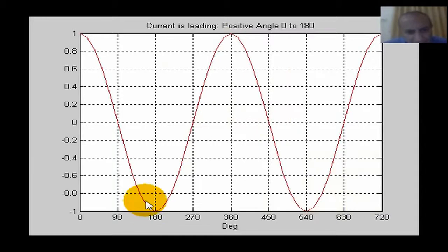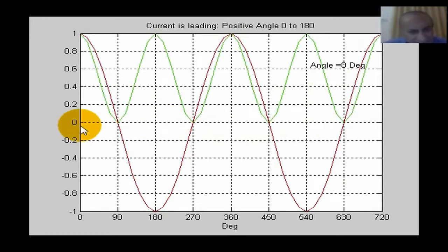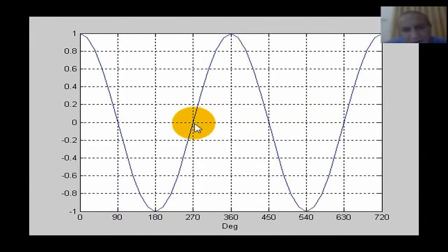So the negative with the negative here is a positive, and the positive with the positive is a positive. So that's why we have double the frequency. Now the power will come out in green, and we'll see that in this case it is all positive power. This is the case of a simple resistor. It absorbs power all the time. If we have zero voltage, it will result in zero power.